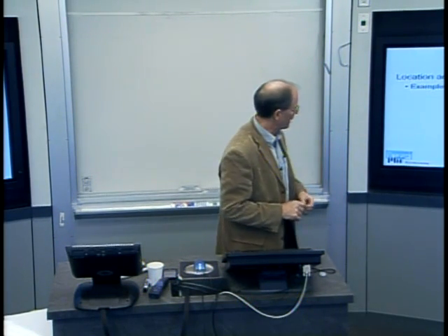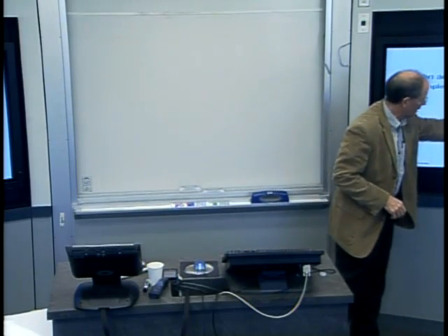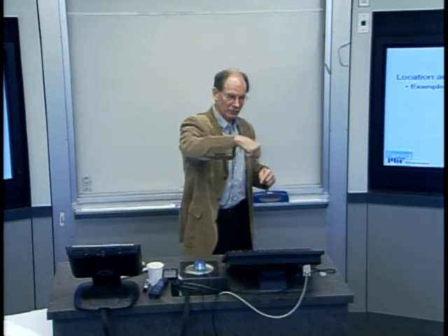This is meant to be a picture of a robot moving it around. So the robot is very important in this case because it's providing the motion and moving the laser tool. And of course, this has been taken to extreme with femtosecond lasers, which at any given instant will only ablate material in, I don't know, submicron areas. So you can really localize it if you want to.